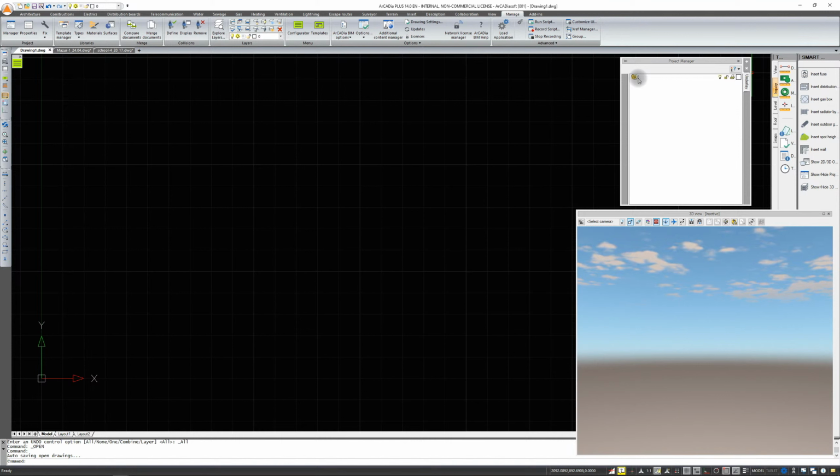You can turn them on. To turn it on and off, we have this bulb. To block or unblock it, use the padlock. You can turn printing on and off with this blue printer. And of course, coloring a given layer. You cannot add or remove layers in this window. It is only a change of visibility, or, for example, blocking a layer.